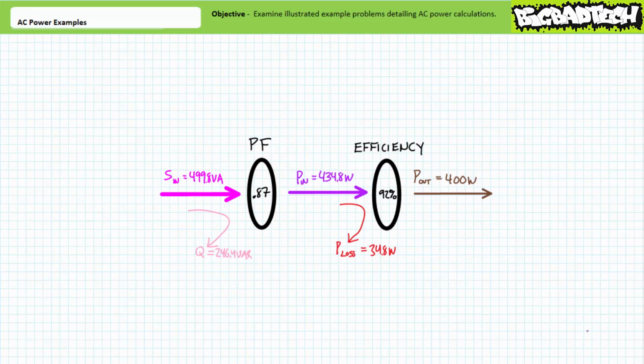Is power factor synonymous with efficiency? No, it is not. Apparent power is composed of two dimensions, real and reactive, both of which are necessary for the proper operation of an electrical device. Power factor merely removes the reactive portion from consideration for the purposes of efficiency calculations.